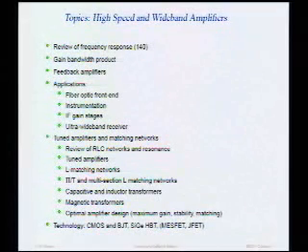Now, silicon germanium bipolar is a lot like standard bipolar that you guys know and hopefully love, but silicon germanium transistors are actually HBTs. They're heterojunction bipolar transistors, which means that, from your perspective, the small signal model looks the same. Only difference is that RB is smaller and FT is higher, so it's nicer.